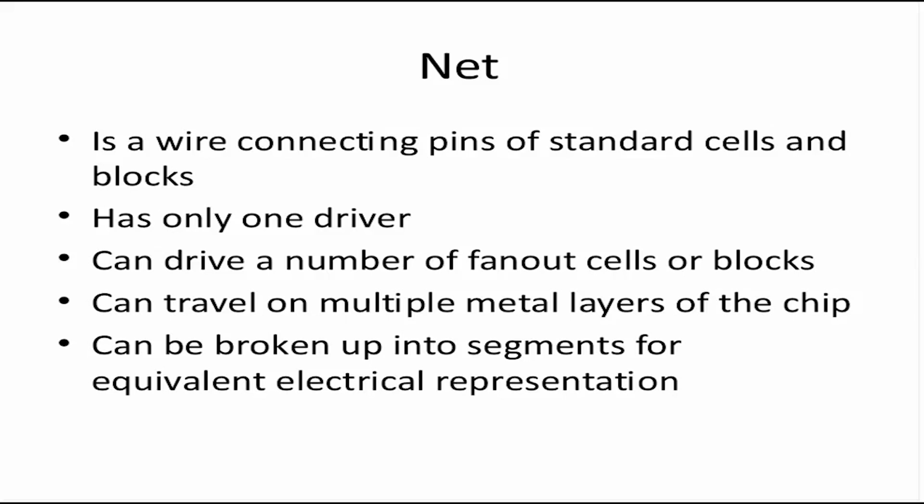One of them will be in a tri-state at any given point of time. So effectively there should be only one driver on a net. What is a driver? A driver will be a cell. The cell will drive the net value to either 0 or 1 depending on the logic state. So it has only one driver for any effective calculation.